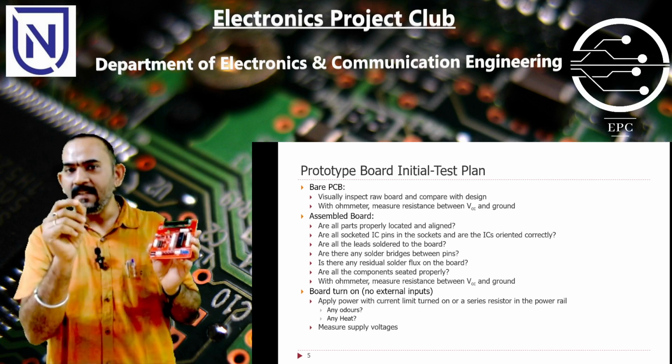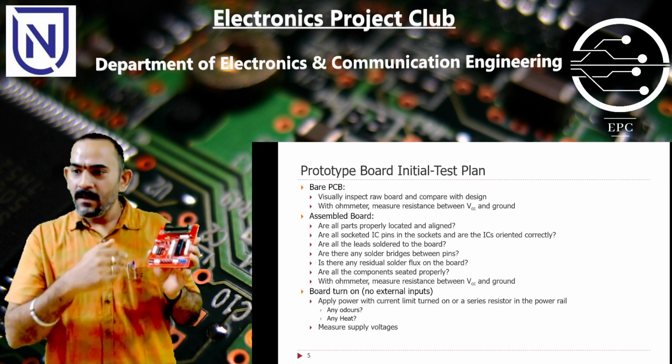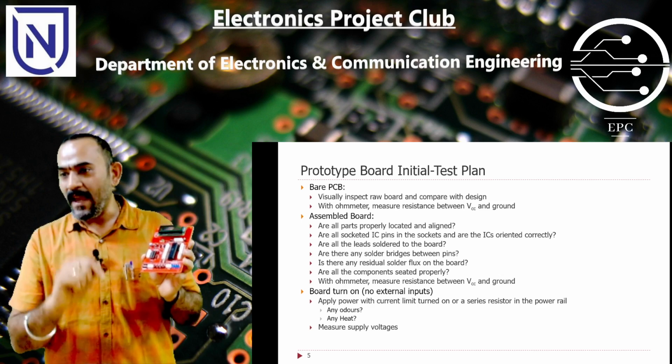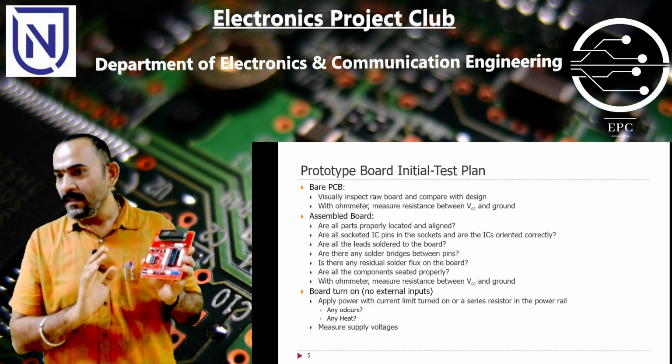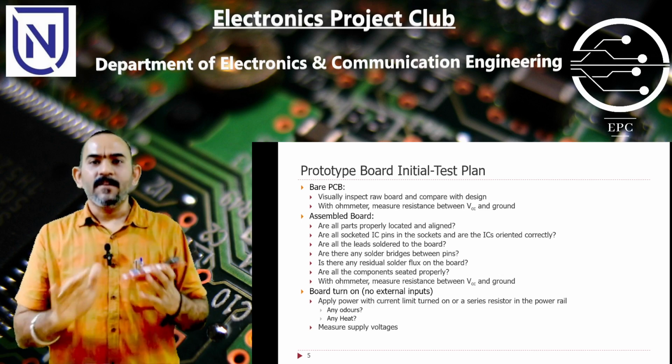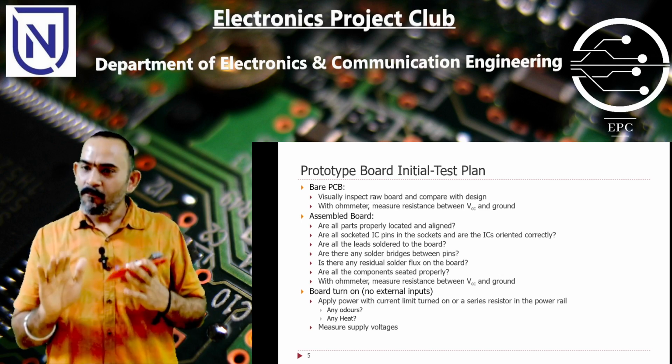And if it is a very thin trace, the trace itself might break over continuous use, because it starts behaving now like a fuse wire. Okay, so it will break first. So we have to be careful. So we have to keep the board on for some time and see whether it is working properly.